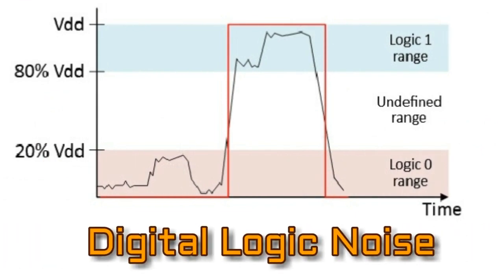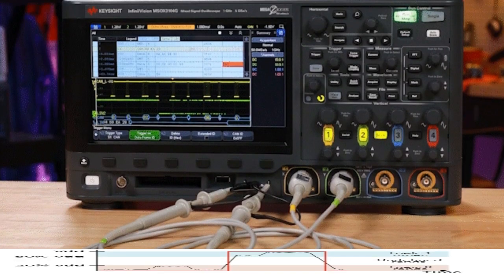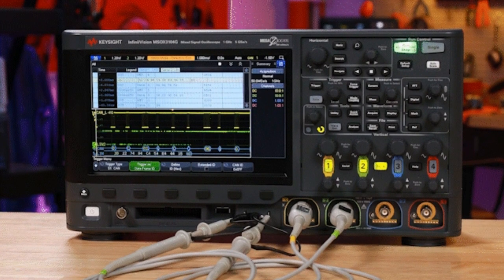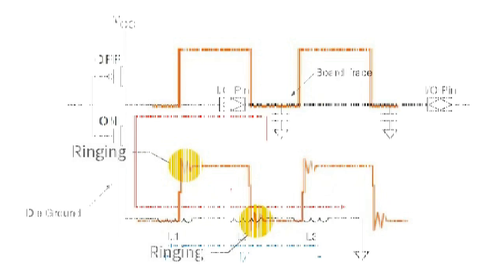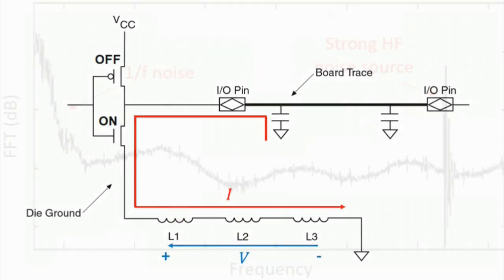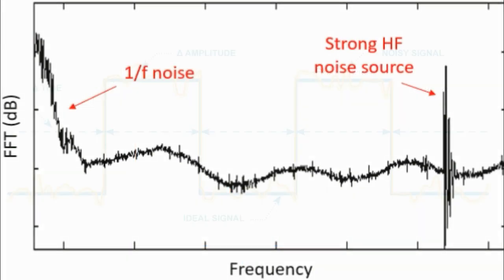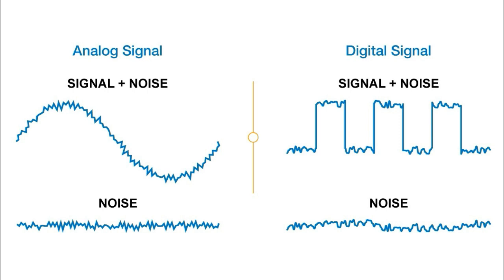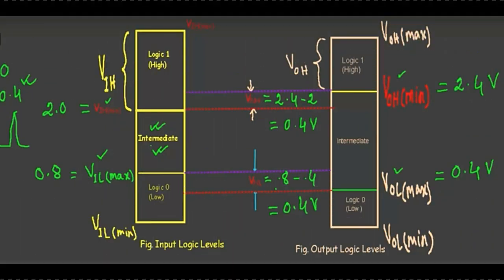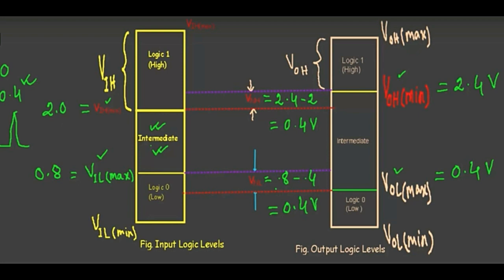Digital logic noise. Noise is the name given to a random and unwanted voltage that is induced into electronic circuits by external interference, such as from nearby switches, power supply fluctuations, or from wires and other conductors that pick up stray electromagnetic radiation. Then, in order for a logic gate not to be influenced by noise, it must have a certain amount of noise margin or noise immunity.